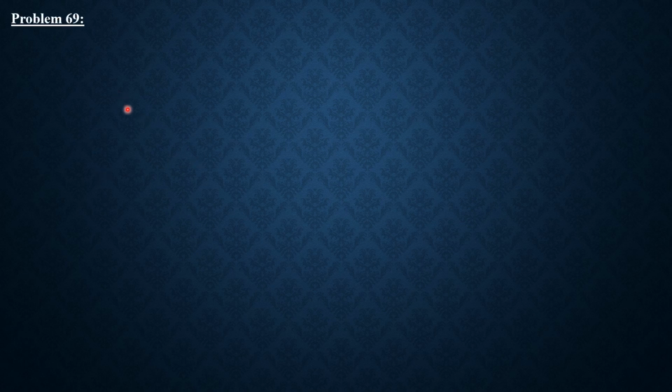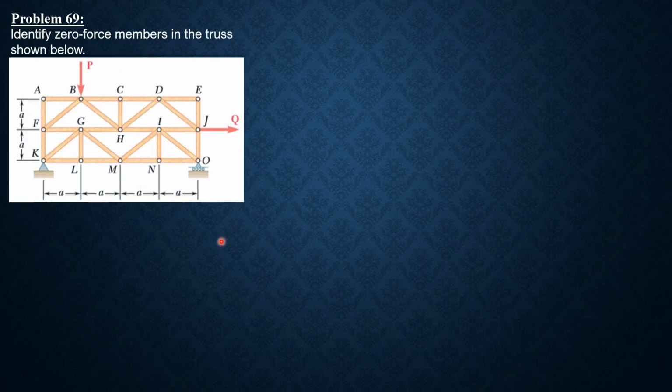And this is the final problem for this series of problems. Identify zero force members in the truss shown below. So this is the given figure. And if we take a cursory look, we have case 1 here. So at joint A, there are 2 meeting members and A is unloaded. Automatically AB and AF would be 0. Summation of forces in X is 0, so AB is 0. Summation of forces in Y is 0, so AF is 0.